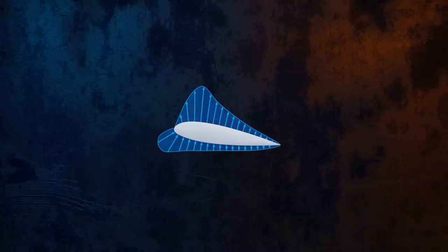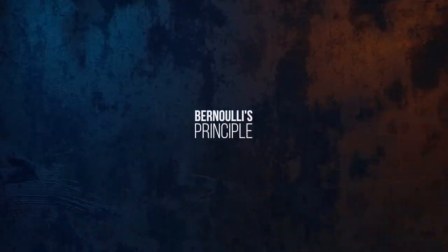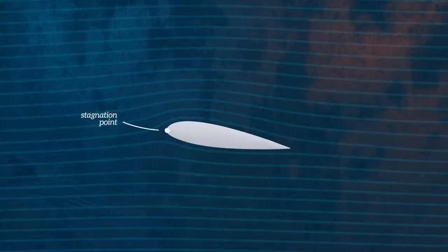The answer to this question is complex, and there's much debate about the best way to explain it in a concise way. We can broadly split the different explanations into two groups, those based on Bernoulli's principle and those based on Newton's third law. Bernoulli's principle explanations focus on the velocity of the fluid. If we look at how fluid flows around the airfoil, we can see that close to the leading edge, there's a point where the fluid velocity is reduced to zero. This is called the stagnation point.